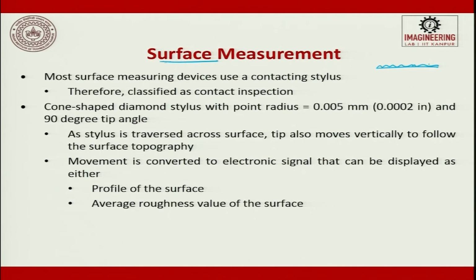If the surface is undulated, there are a lot of sharp edges. These sharp edges can be stress concentration points when we do a fatigue cycle, and the components can fail. Or when you have a sharp edge, when water gets deposited, it can start corrosion from there. So, it is always advisable to have a flat surface as compared to a rough surface, for certain applications.